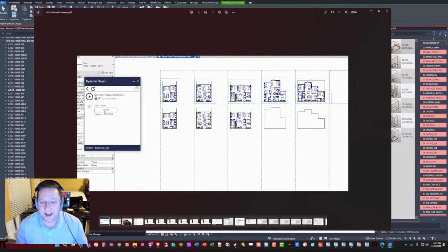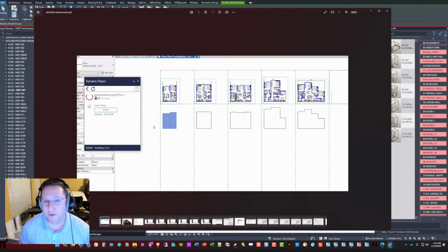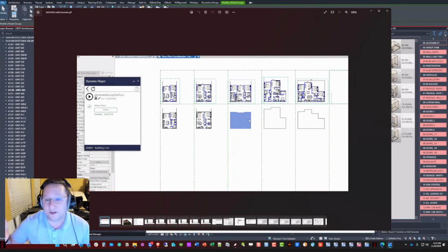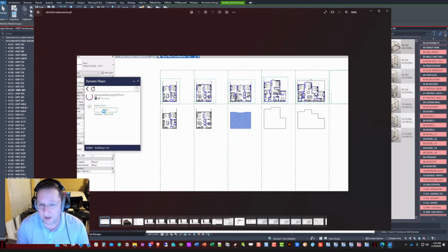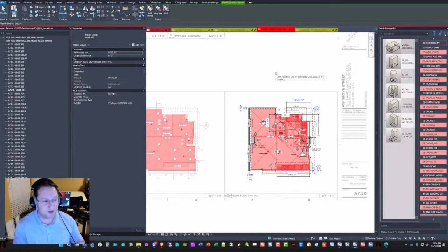So in that case, now you've got the lightweight floor, right? And of course, if any of you remember the legendary block diagrams, you can actually just have a floor type that's like 10 feet tall. Right. And now you have actual stackable blocks, but then you can convert it into the model group, and you'll see here, back to the question from earlier, here's groups with all the furniture in them, of course. So that's just a fun little trick. I won't say we do that on every job because we don't, but it's really fun to be able to just drag floors around and then swap them for groups later.